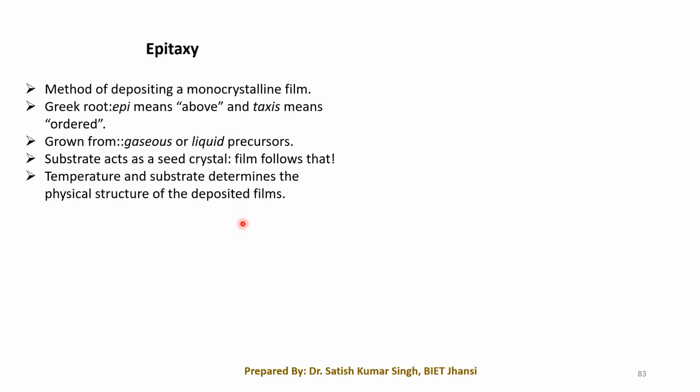Whatever specification you want, I want a particular layer onto the substrate onto which we want to make a circuit. So either we can go for making a complete new wafer, so that it can be directly used for making the circuit, or we can take an already available wafer, modify it, and grow a particular layer onto it that will have our desired specifications.